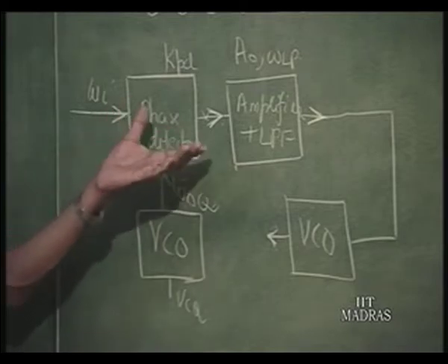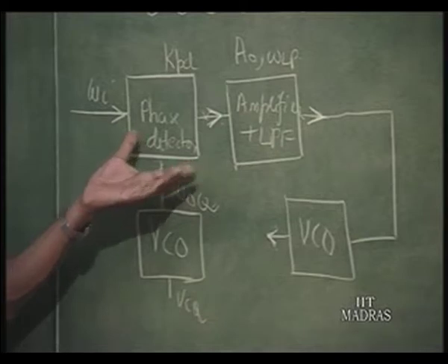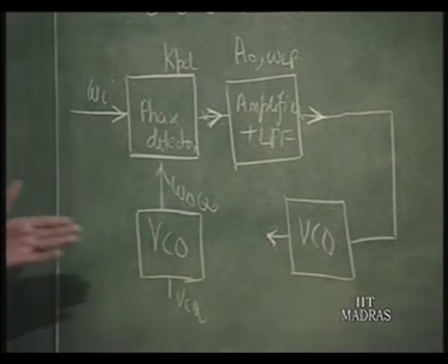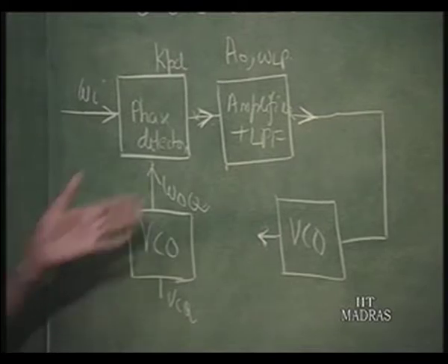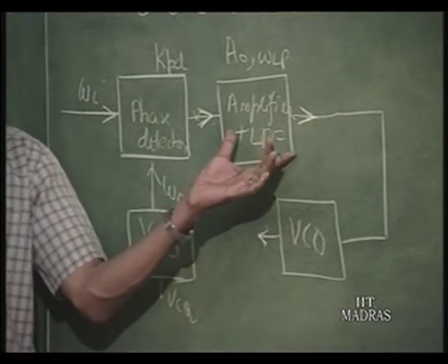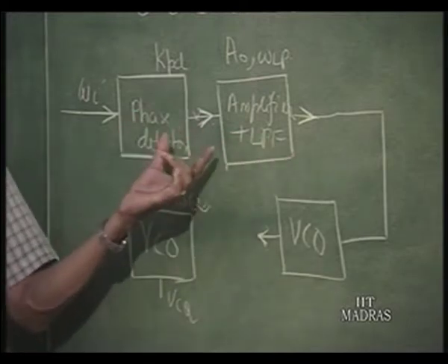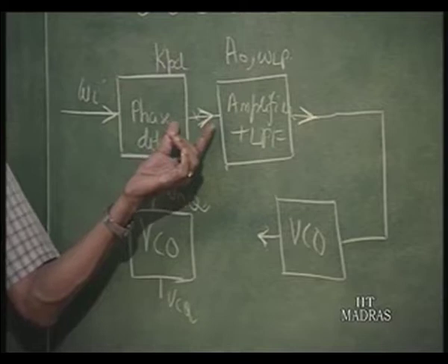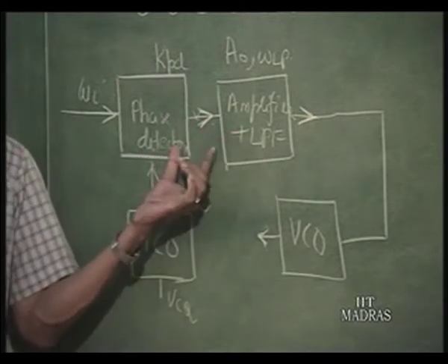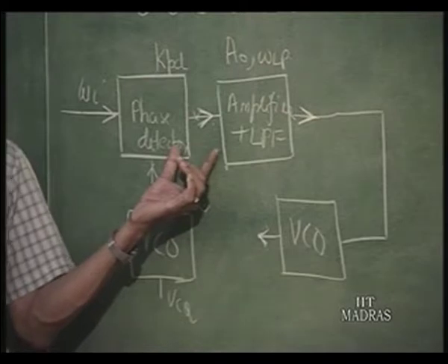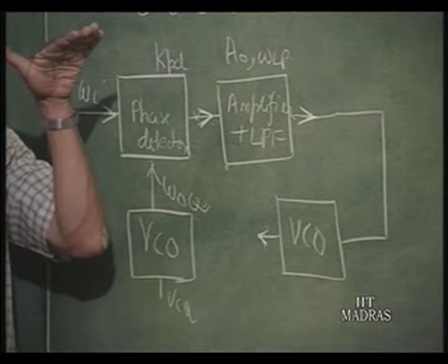So, it is not a square wave or anything like that. It is a waveform whose frequency is changing. But out of that we want to take only the lower frequency component omega I minus omega naught q. I am assuming for practical purposes that it is responding to only the sine wave part of the lower frequency, which is also not correct strictly, because it is an amplitude limited waveform.